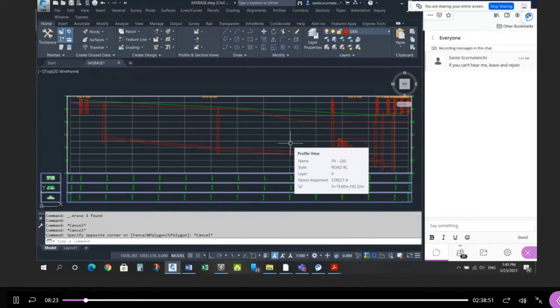If it's wrong, if it's off a little bit, do you need to correct it? Technically, yes. But if it's close, I'll allow you to continue without fixing it. Just make sure that your slopes and your elevations are within a few millimeters, or 0.02% or whatever on the gradients. I've graded this part of it, and if it was close enough, I kind of let it slide.